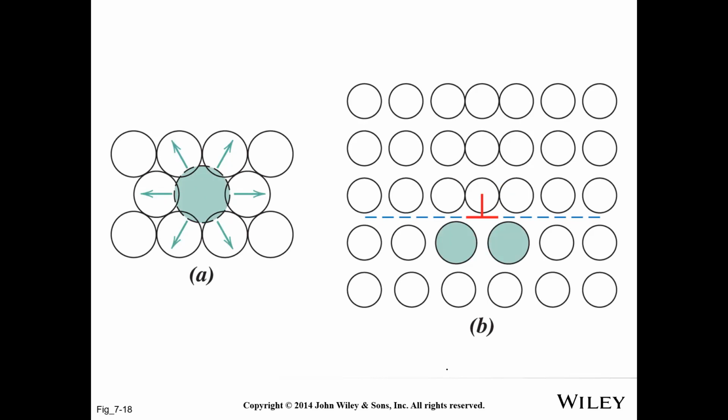And here is a bigger atom. It likes to sit below the dislocation because we already know there's a tensile field there. We've got a compressive field associated with that big atom, so it kind of likes the spot below. But the point is, it likes this, so it takes more stress to get the dislocations to move.